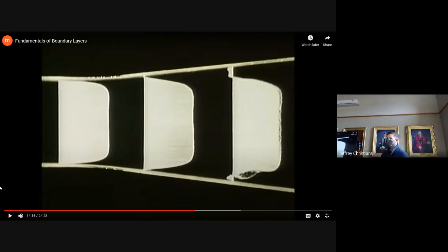Okay, now this is a really important image to look at. What's happening right there near the wall? Our flow has turned around and started going in the wrong direction. Why did it do that? Well, let's think about what the different forces in the system are. Our channel is diverging, it's getting wider. So we have low pressure on the left and high pressure on the right.